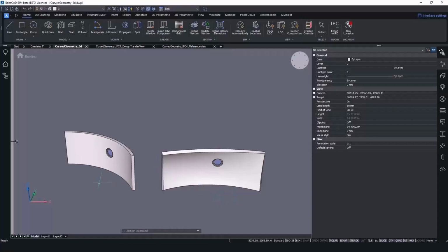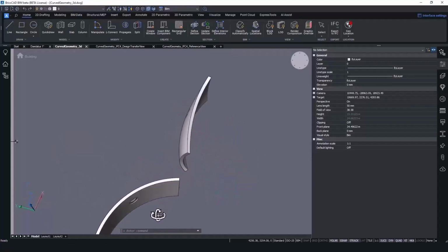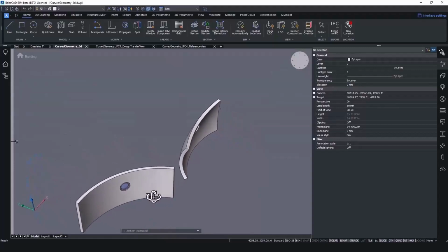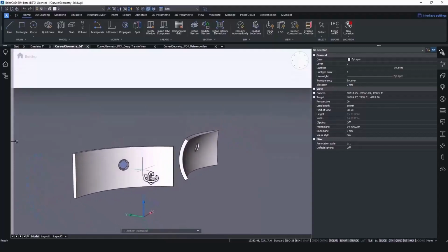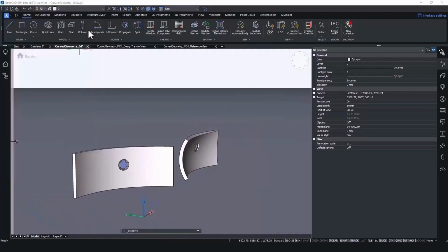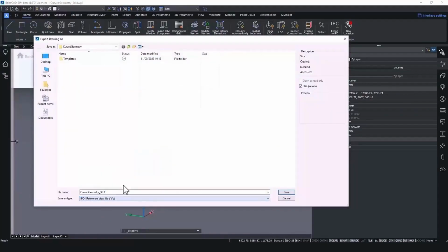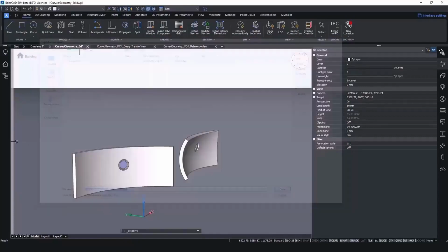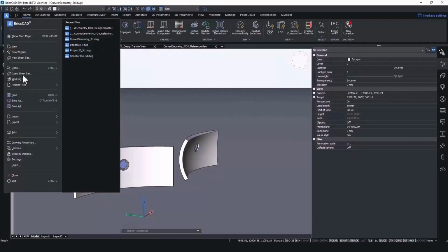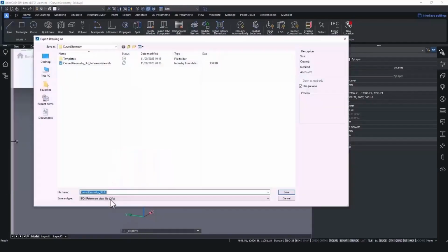So let's dive a little bit deeper into this IFC4 reference view and see what it actually means. What is the difference between the IFC design transfer view that we can find next to the IFC reference view? Well, IFC reference view enables you to make a simplified version of your model. It is the IFC4 reference view that the IFC4 certified programs are validated against. So this is why we implemented the reference view export, so that more programs can read the simplified file.